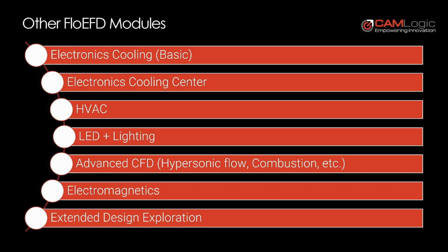And then finally is extended design exploration, which is very similar to that design optimization feature I had shown for Solid Edge Simulation Standard. It's the same idea. You can input design parameters, design limits, simulation limits, and it will optimize your design by making various changes to those design parameters. So almost an identical concept, but this would allow you to do this with CFD parameters, both temperature and fluid flows and other goals.